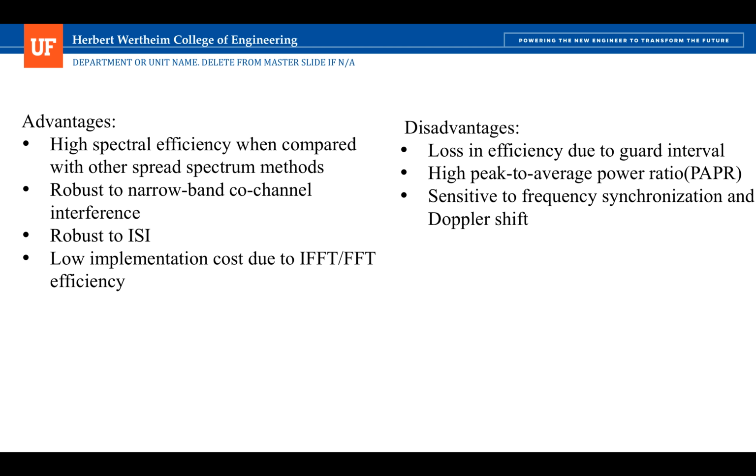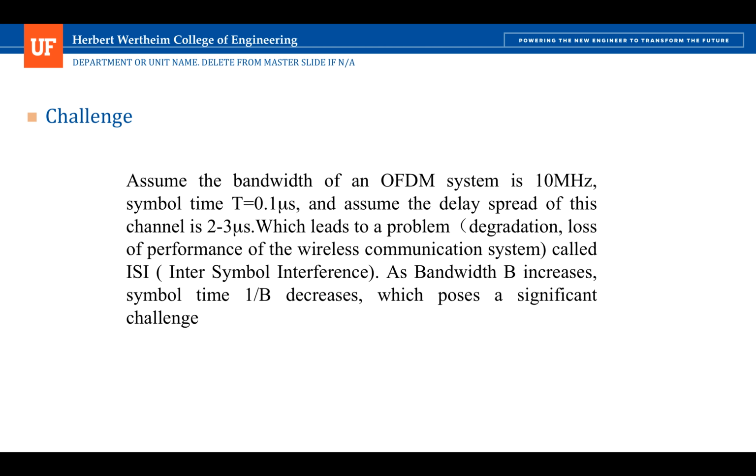For its disadvantages, it has loss in efficiency due to the guard interval. It has a high peak-to-average power ratio, PAPR, and it is sensitive to frequency synchronization and Doppler shift.